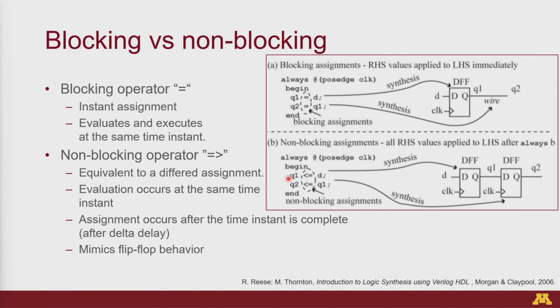So a simple question of when to use blocking or non-blocking: did you intend to design a flip-flop? If yes, then you use a non-blocking operator, else just use a blocking operator. That should simplify when and where to use each.